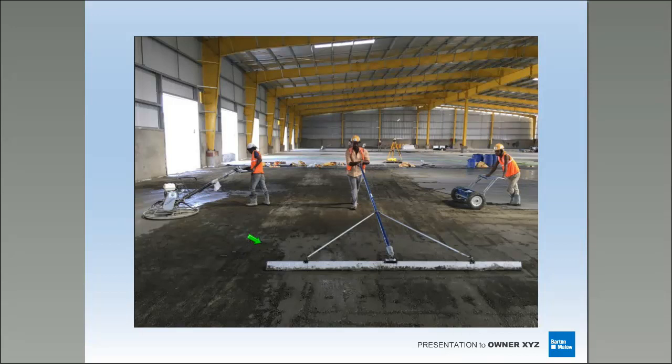If I wasn't polishing the slab, I'd probably be okay with some of this. I see a lot of inefficiencies here with the placement, either the rebar or whatever. I see a lot of lines here that have got to be filled in with cream. It's just not a real good example of how it should be done.